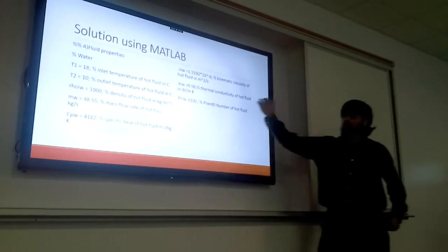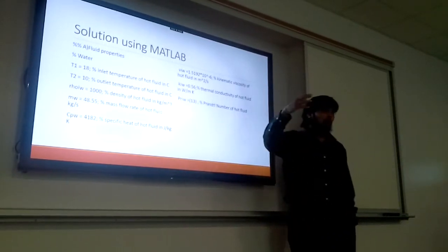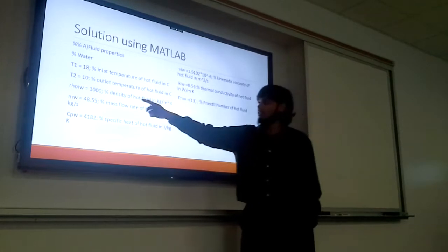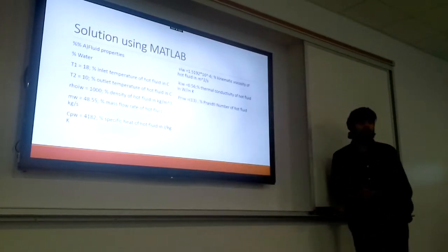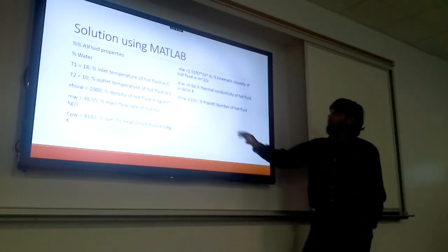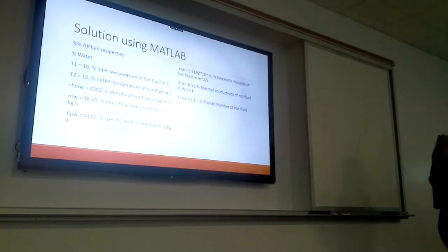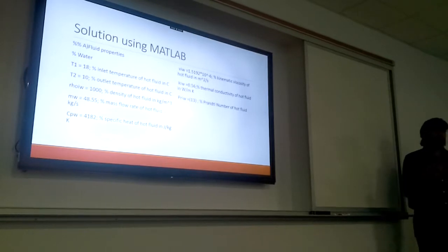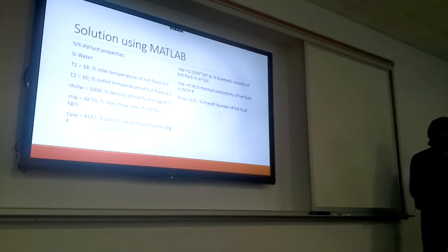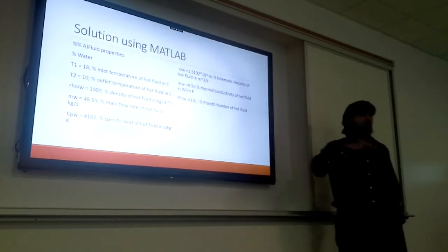Then you can take the average of that, and based on that, you can look up in your table and get the densities and the mass flow rates and so on. If you notice, I didn't do much averaging here, because liquid water, what do we know about its properties? It's incompressible, so as a result a lot of the properties stay relatively constant.